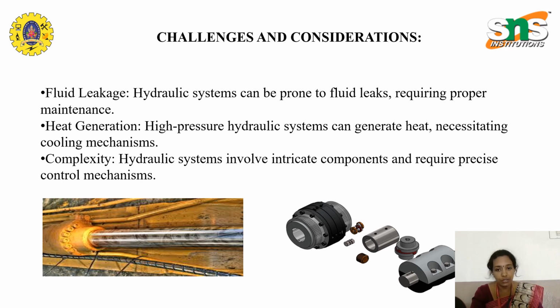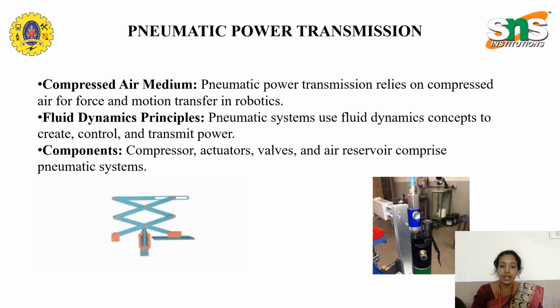These are the challenges which are to be considered for the hydraulic power transmission system. The hydraulic system can be prone to fluid leaks. This requires proper maintenance. High pressure hydraulic systems can generate heat, necessitating a cooling mechanism. These systems involve intricate components and require precise control mechanisms.